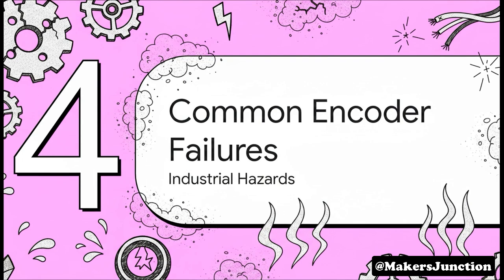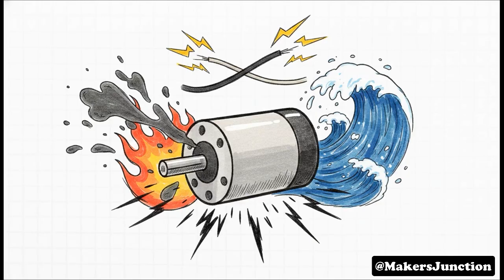Let's look at Section 4, common encoder failures. Consider the intense, really gritty man versus nature conditions of a steel mill. You've got extreme heat, grease, and microscopic metallic dust just flying through the air. If that dust gets inside the encoder, it causes disk contamination, instantly corrupting those super delicate optical signals.